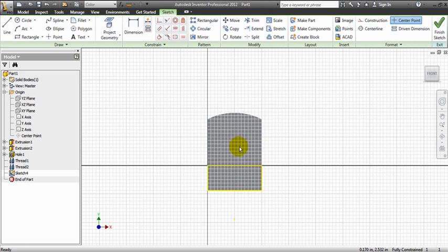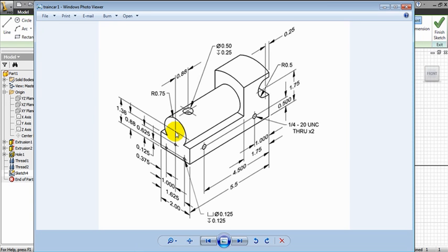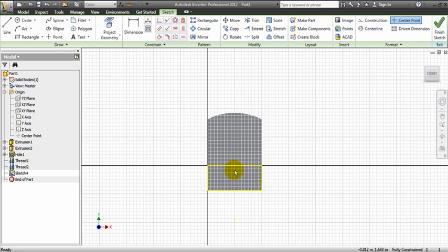And I'm going to create the little circular shape here. And this circle shows me that the radius is 0.75, so that means that's half the diameter. So I'm going to double it. And it also shows me that the center of this circle is 1.38 from the base. If I follow this line over with my eye, I'm going to make a circle that's 1.38 tall and 0.75 times 2 for the diameter.